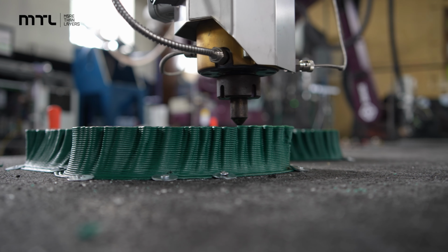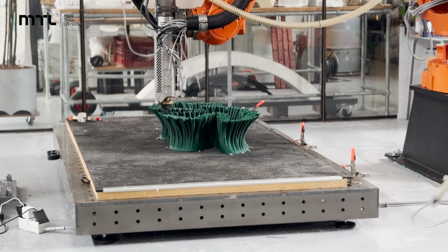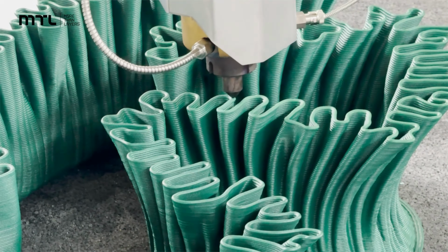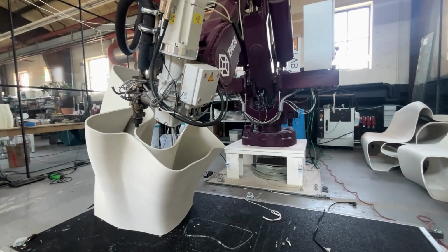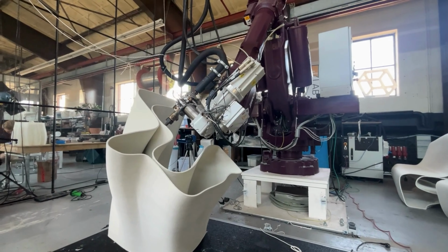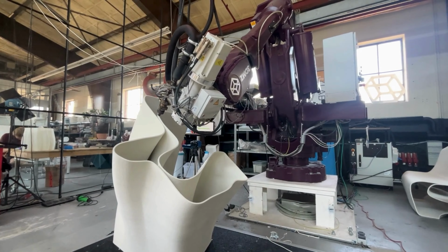As a designer, you are not only designing the shape, you're also designing how it's made. You are designing the path the robot takes, the direction of the layers, the speed, the temperature, and it all affects the result. Also, every robot has its limits. It can only move within a certain range and at certain angles. And if your geometry falls outside of that range or outside of those angles, it can simply not be printed. So compared to a gantry system, which just moves in straight lines, a robotic arm has 6 or even more axes. That means that it can tilt, it can rotate, and it can follow curves. And that opens up a lot of creative freedom, but it also adds a lot of extra complexity.